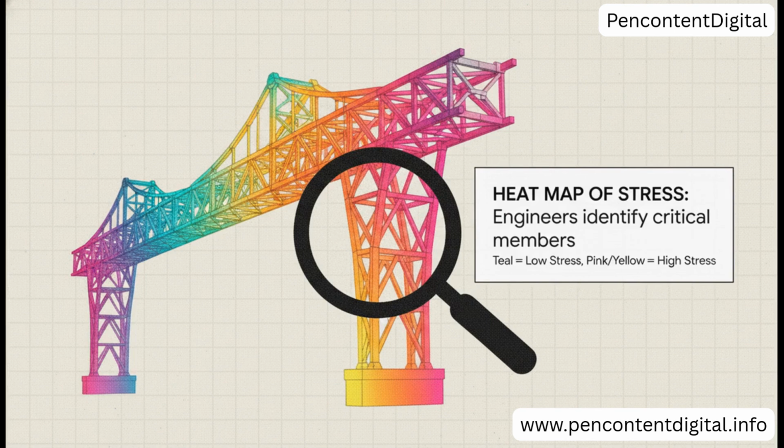The analysis basically creates a heat map of stress across the entire structure. It shows engineers the exact beams or columns, the critical members that are taking the most punishment. That's how they know where they need to add more strength, maybe by using a thicker beam or a stronger material.